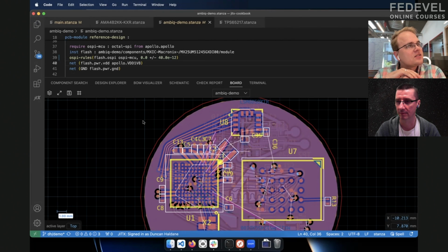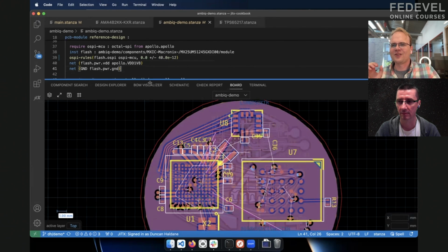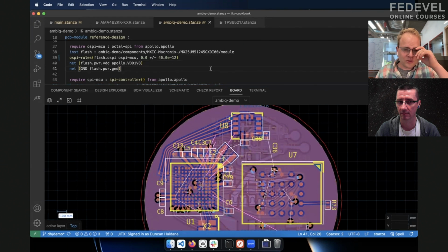And now I think it's more automation, so more better search in the router, so you can do larger banks of signals and have it negotiate now that it has all of the timing constraints in it. And then I think a little bit of that is going to be placement as well, saying I have a very clear definition of subcircuits, right? Here's my processor, here's my flash. You should be able to collect those up and say all right, give me a great local layout for this, and then I'm going to drag it into place, and then I want it to adjust a little bit to its surroundings. So I think that kind of layout automation is coming next.